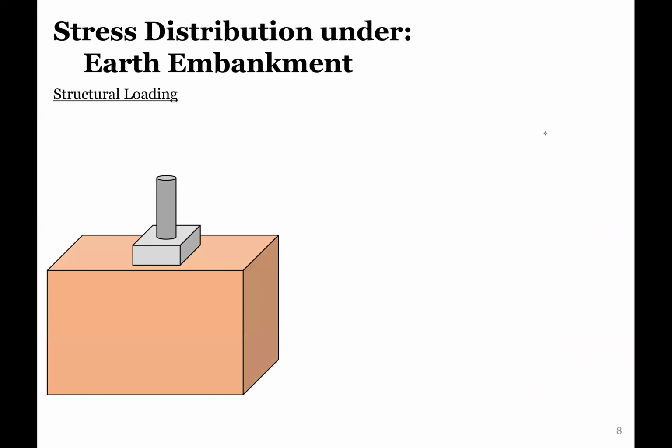So we know from structural loading, right? Like this P, this column load is going to be taken from the dead loads of the object, the wind loads, the gravity loads, the seismic loads, something from the structural engineer. And this is going to be applied over a cross-sectional area. And sorry, this is another typo here. This should be feet squared in the units that we're using here.